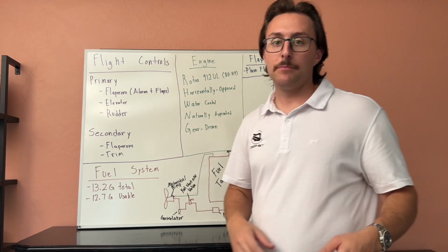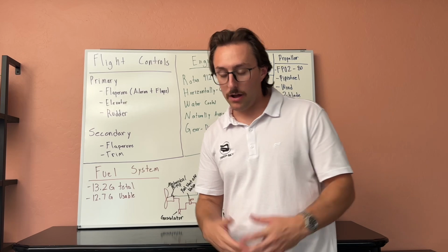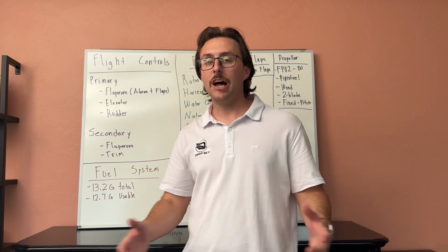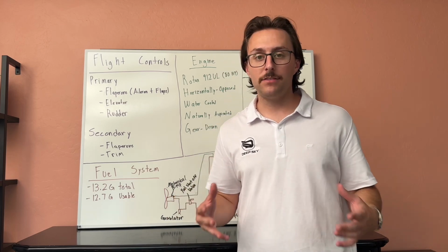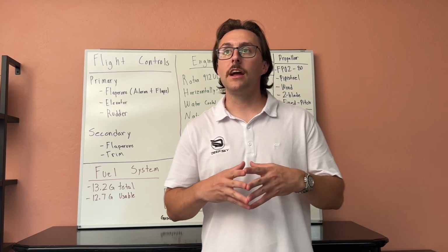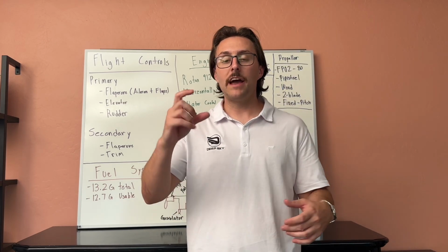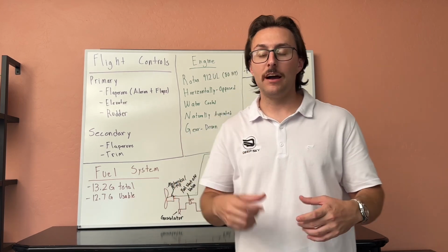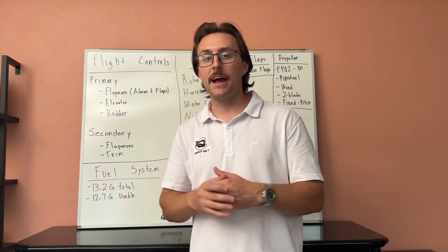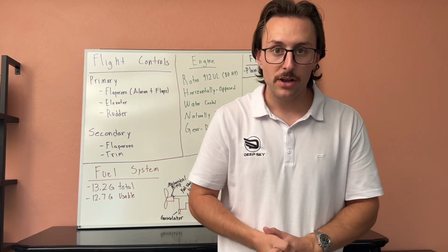Now let's go into the flaps. What kind of flaps do we have? Well, it's very simple. There are lots of different types of flaps, but on our aircraft specifically, it's just going to be plain flaps, as opposed to, say, a slotted flap, which has a gap between the wing and the flap itself, which ours does not. It's just straight back into the flap, so it's just a plain flap. Real easy.